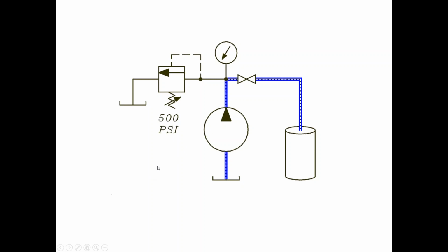Right? So, suppose I close that hand valve. All right, now what's going to be the direction of flow? Well, the only direction we have left is to go through the relief valve, so that's what's going to happen when I turn the pump on.